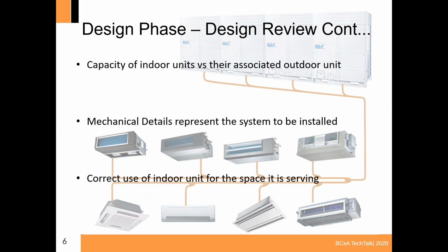Other things to look for. The capacity of your indoor units versus their associated outdoor units. Some manufacturers allow their outdoor units to support up to 50 indoor units. So it's worth it to just quickly go through the schedule, add all those up, and make sure they're not over the capacity of the outdoor unit.